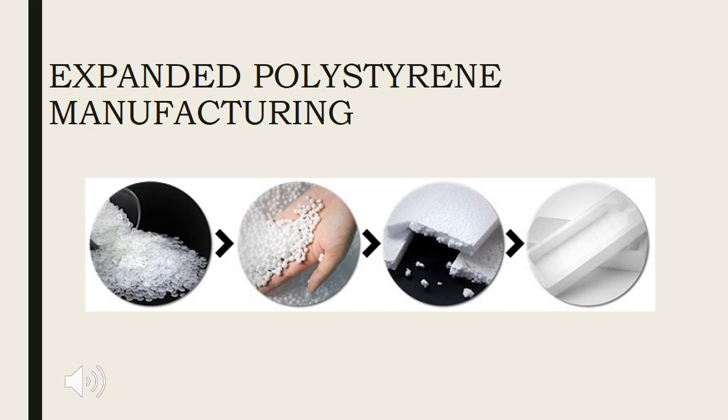Polystyrene granulate is pre-foamed at temperatures above 90 degrees centigrade. It means the polystyrene solid granular is converted into foamed granulate above 90 degrees centigrade. This temperature causes the foaming agent to evaporate and hence inflates the thermoplastic base material to 20 to 50 times its original size.